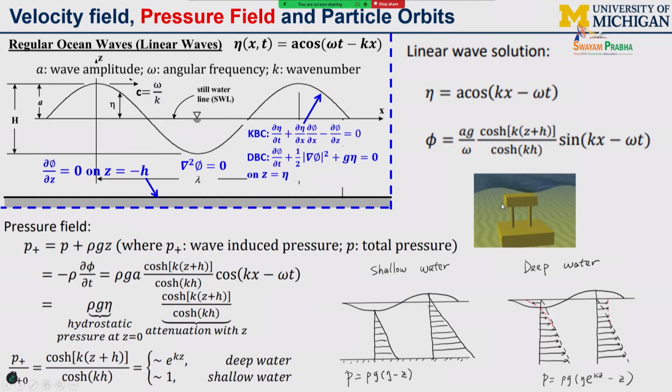Therefore, you just imagine that. Some companies like Carnegie Wave in Australia develop wave energy converters submerged into the water, and actually for military applications, you don't want anything outside on the surface, right? You submerge it into the water. It cannot be too deep. If it is too deep, the dynamic pressure decreases too quickly, right? It's the same pattern, e to the Kz. So you try to keep it as close as possible to the surface, but submerged in the water.